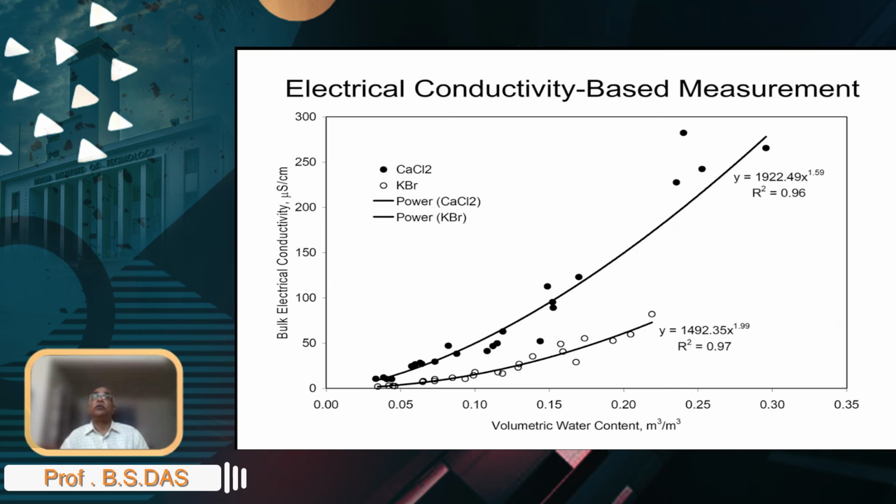But nevertheless, if you are to make a 4-probe electrode, you probably have to spend something like 20-30 rupees, and should be able to have an electrical conductivity probe by soldering them, and then have some kind of a probe holder, and then you insert them into the ground, and should be able to measure electrical voltages, and set up even a more sophisticated bridge measurement and then have a full-blown device, easy to make.